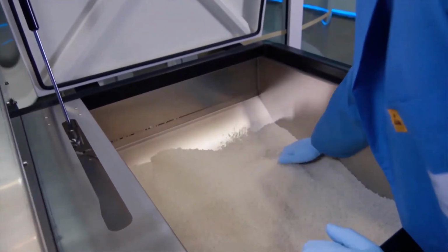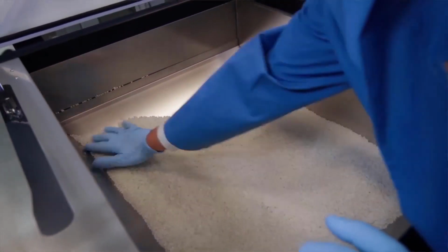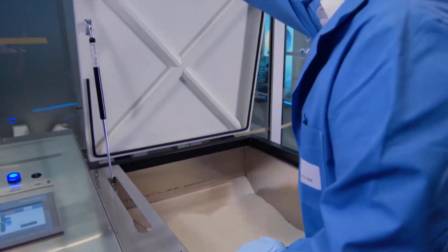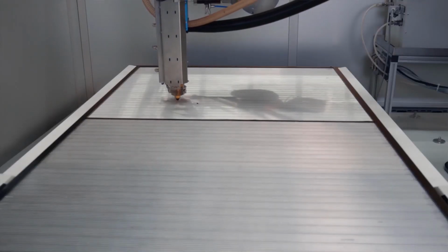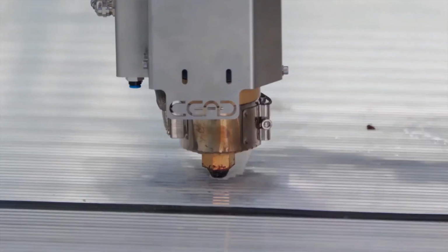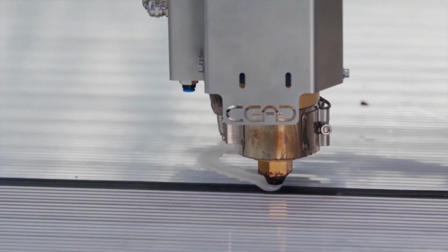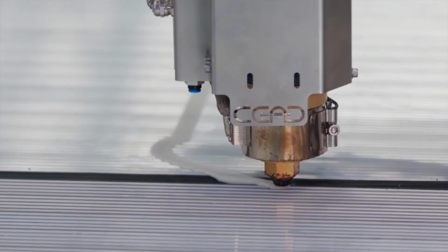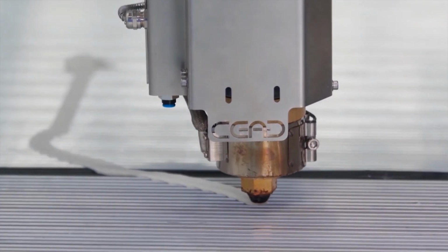So I needed to check the pallets, I needed to refill them, switch on the cabinets, and of course also some warm-up time for the extruder. Then it's very important to start the print process very slowly, because you need a proper bonding between the part and the build plate. It also has a slightly ripped surface, as you can see. And this ensures a proper bonding between the part and the build plate.